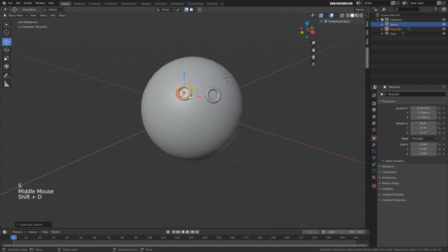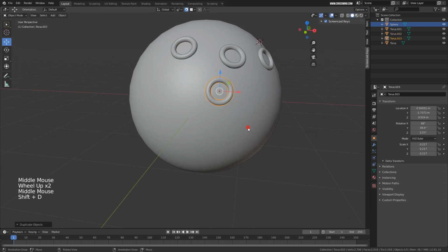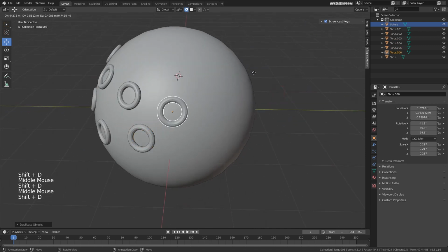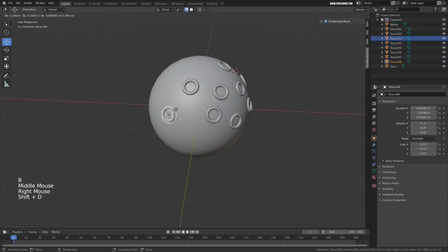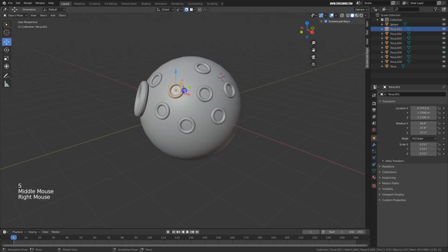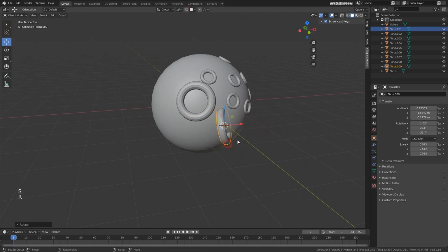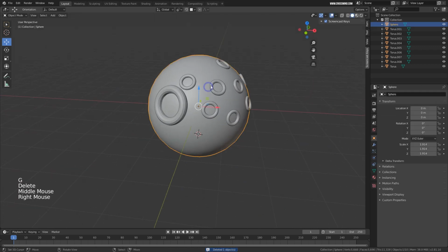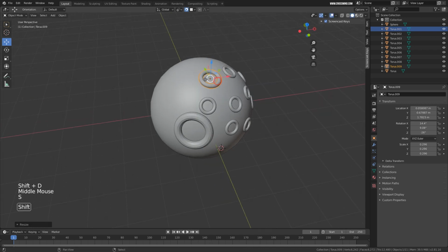Now see, if you want to quickly duplicate stuff, these will automatically pick up the orientation of the surface you are projecting on, and this is so much more convenient. So you don't have to all the time create an object and align it manually. I just want you to know there are options available to speed this task up. You can simply enable face mode and go to align rotation to target and enable these two, and these will work.